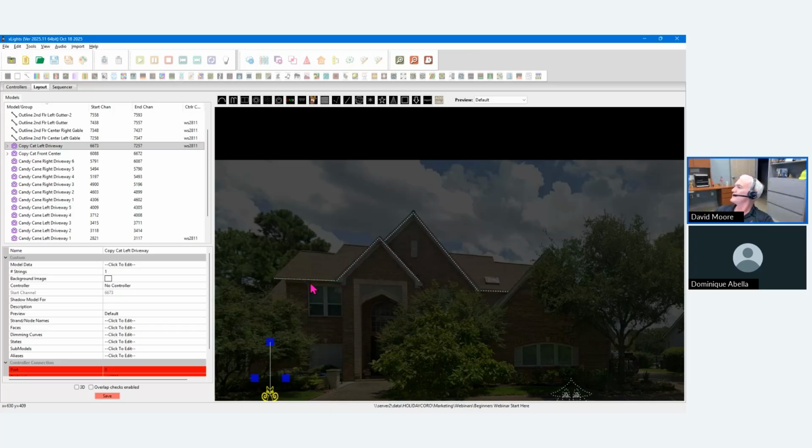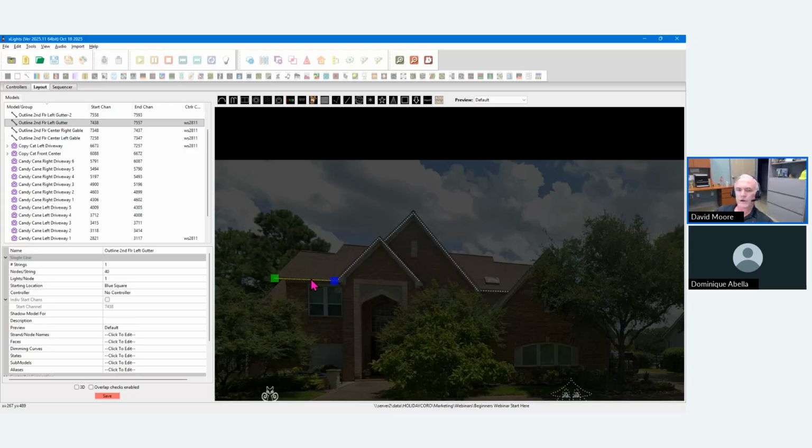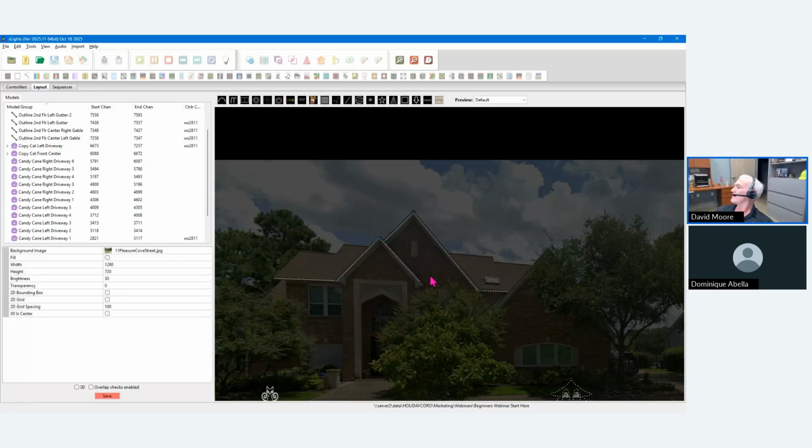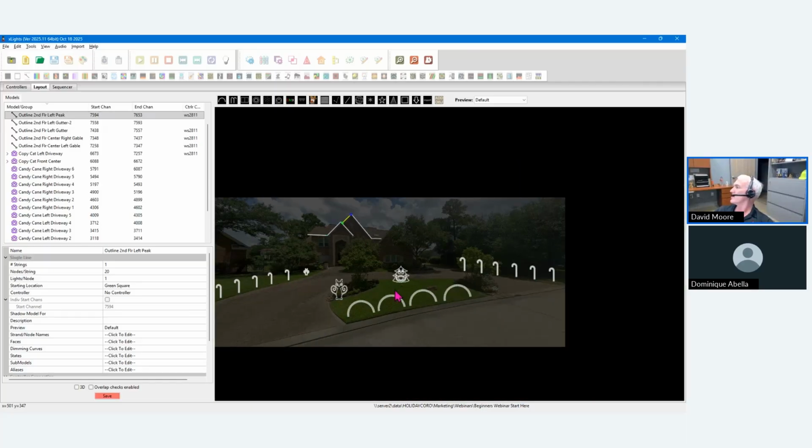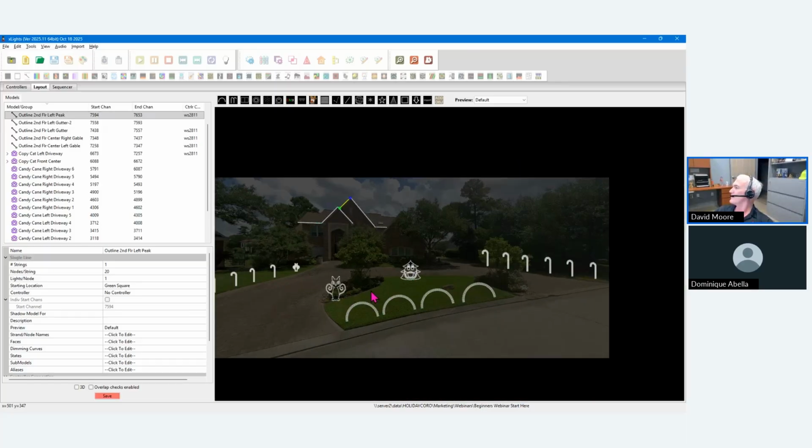So one receiver. So I'll have one output here on this left. Then I'll have another output for this one. This is 2 on these. Or maybe not. And then the third output I'll have here going down and around. And again, we'll just say I've done all the math. There's no more than 200 pixels, and these are 12-volt nodes. So we need 3 outputs. We'll need a 4-output receiver.